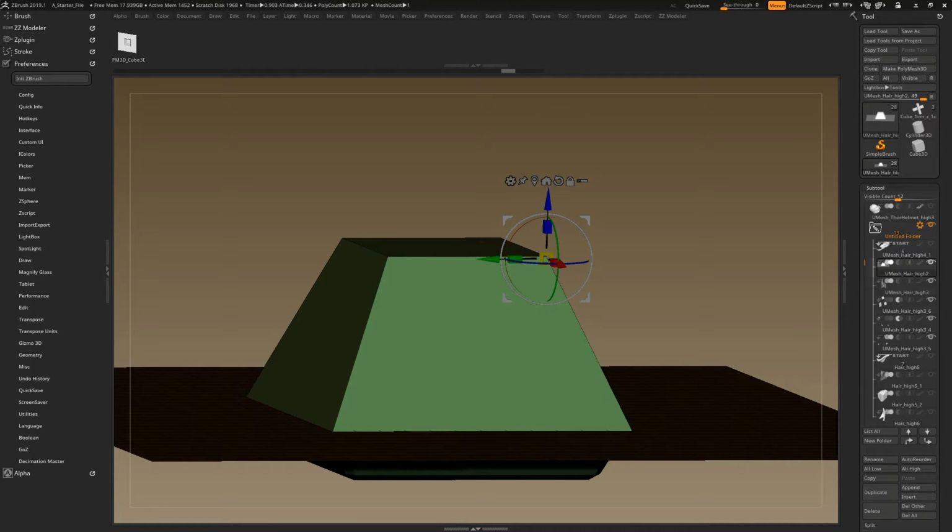It's a really touchy thing, because like I was saying before, if you're using SLA and you're not using light meters and checking your stuff, you can have overbake. If you have overbake at that size, your tolerance is going to get eaten up, in which case the parts aren't going to fit no matter what you do, short of grinding away. And you have shrinkage, and maybe.